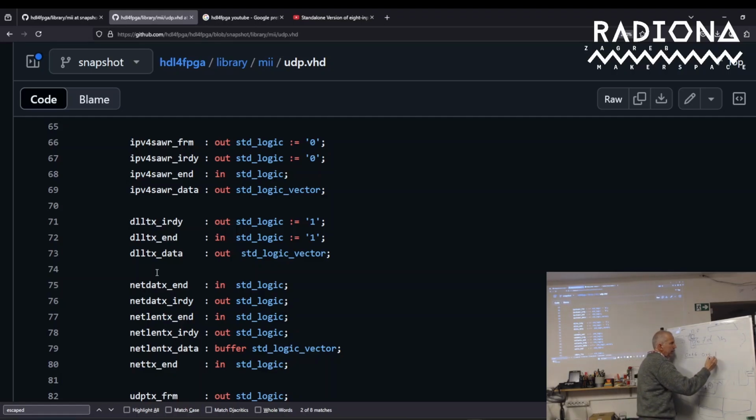And I didn't want that because I have to delay the data for, I don't know, that's what I am doing, I don't remember it that way. You have delayed 4 bytes, probably that is what I was doing, but I cannot find it. And then I check the CRC, and the last 4 bytes of the valid packet arrive just at the same time that I am detecting the CRC. So probably it's that, but I couldn't find it.